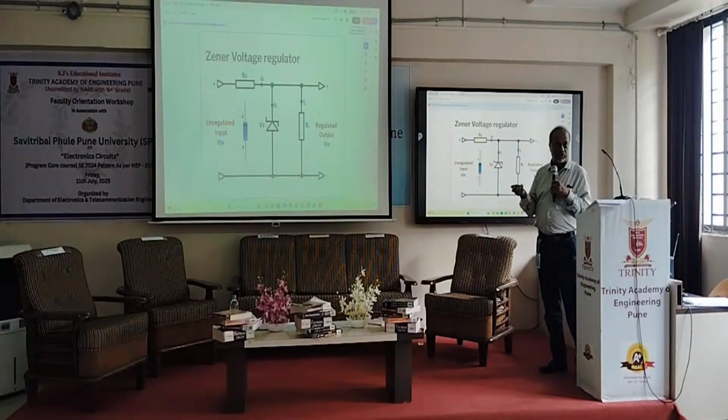And as everyone agrees, in every circuit wherever we use a Zener as a regulator, we need to have a resistance in series with it. If this resistance is not there, that circuit will burn out.